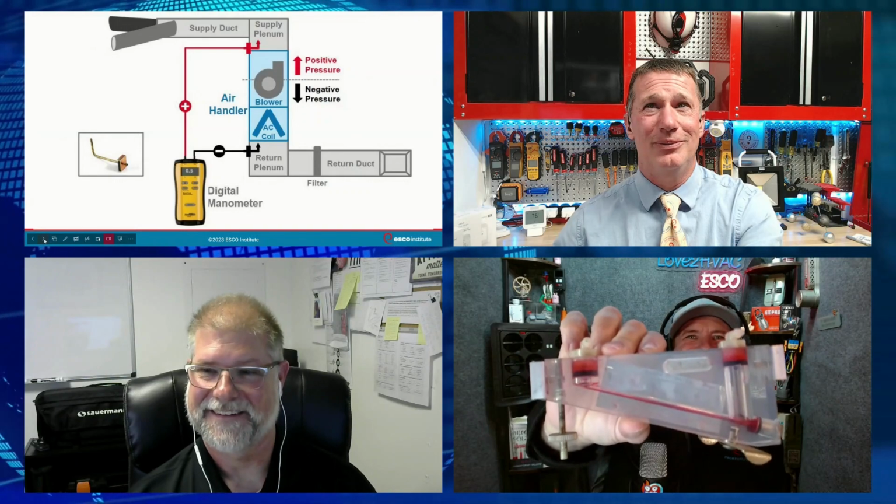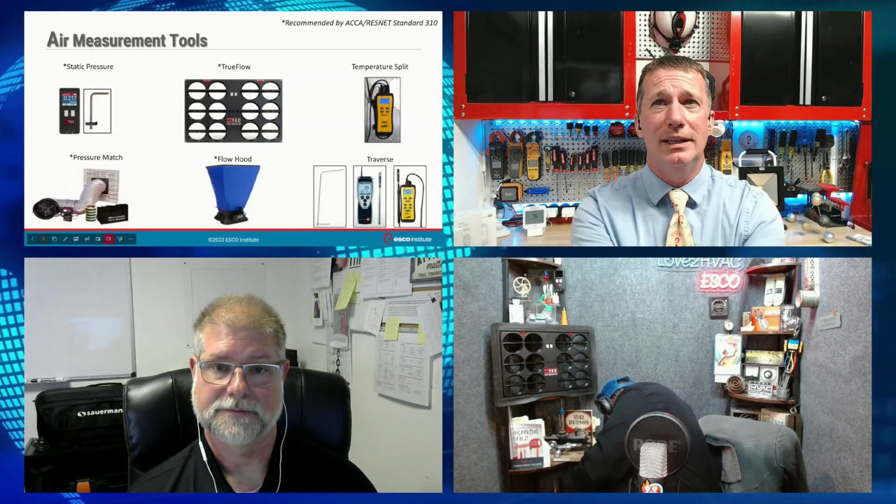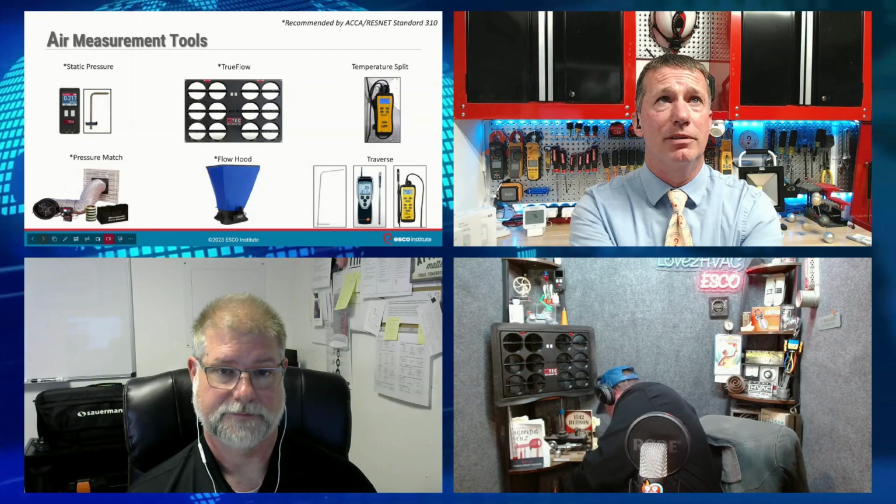All right. So basic fundamentals when we start talking about measuring static pressures. We've been measuring static pressures for almost 100 years in water column forms, right? We've used the magnehelic. Ty's got one right there. That was the practice that we used. I've even seen some of those original ducted systems that had magnehelics installed in the ductwork, especially on zone systems. And so when we start talking about professional measurements, of course, we've seen digital technology, like using digital manometers. But let's go a little further and talk to people about ways that we can even get better, accurate measurements of our airflows.